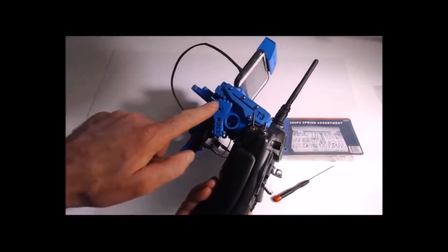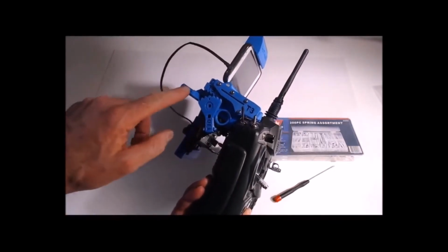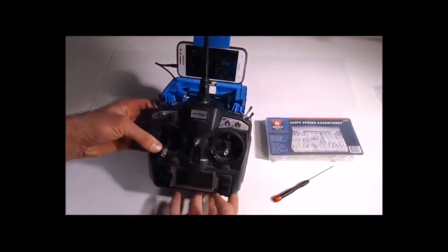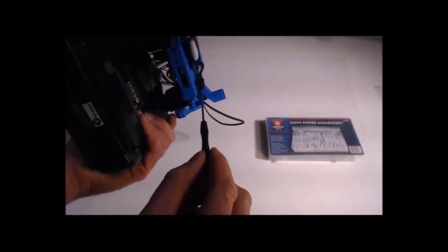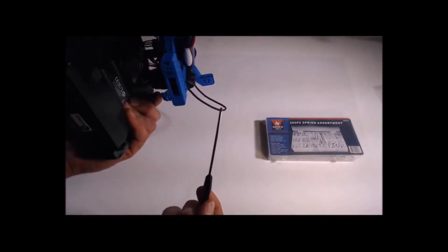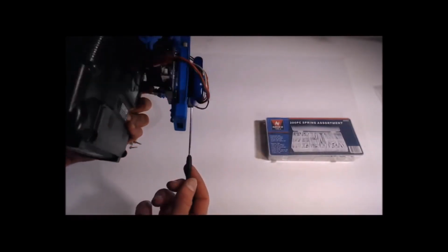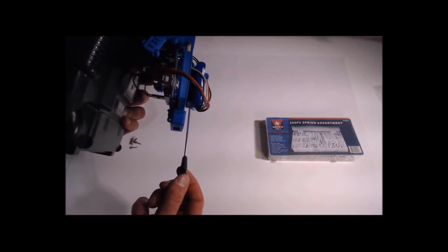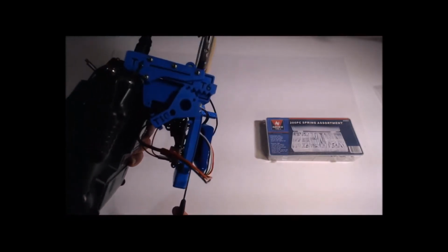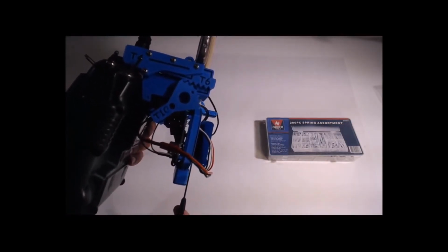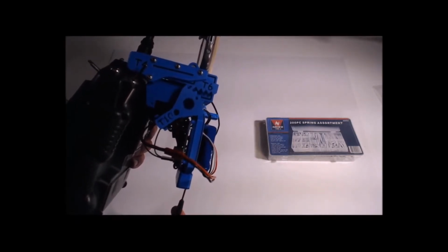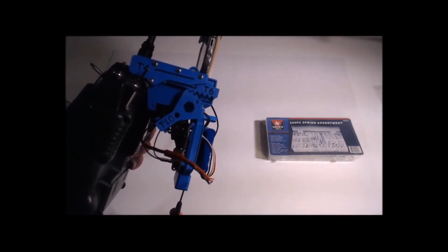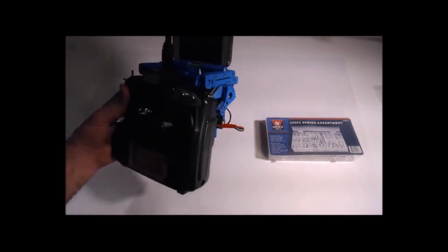So we're going to install a spring next, right there. But first, now on this servo reverser there is a small potentiometer. I use a small Phillips, and we can adjust that servo. It may be riding it hard, making a noise. You can back it off. I'm turning it right there. So just get it kind of loose in that gear all the way back. There we go, we're adjusted.